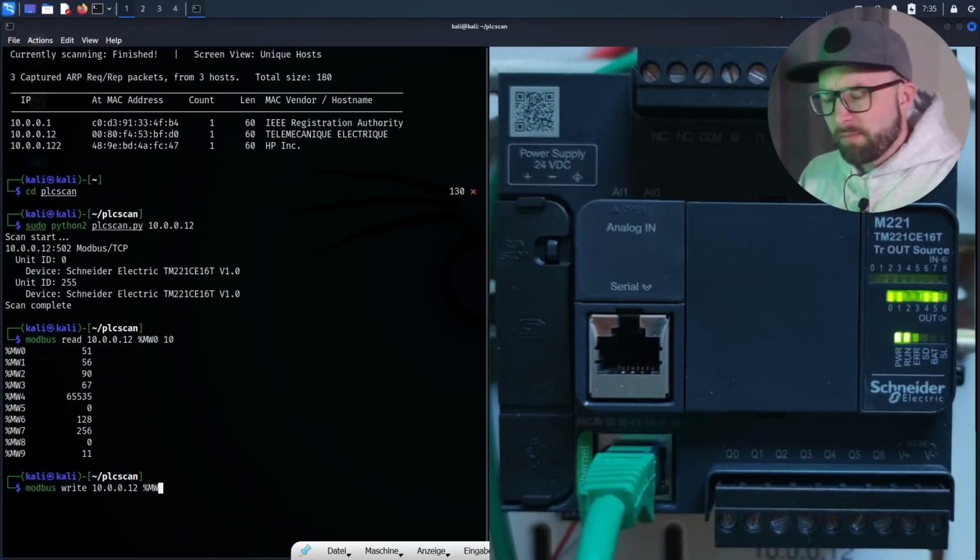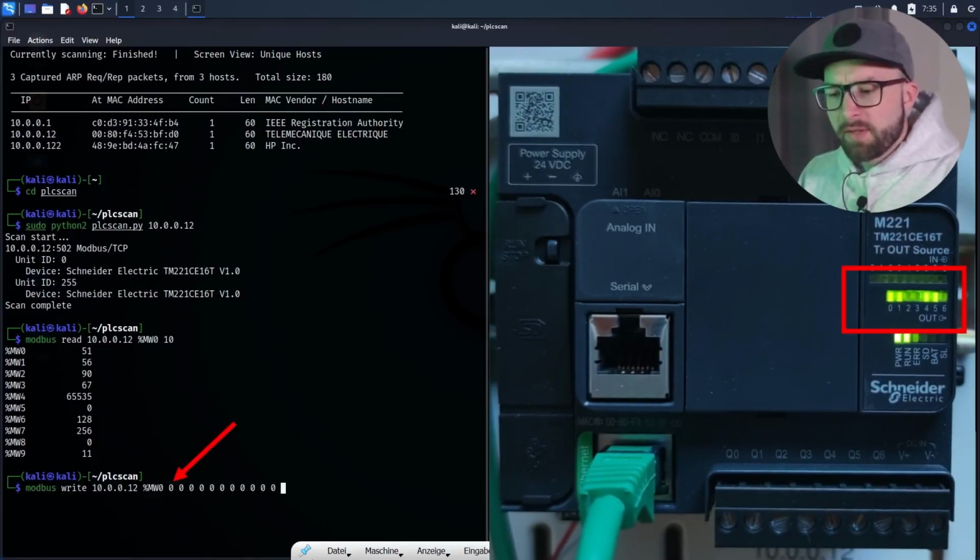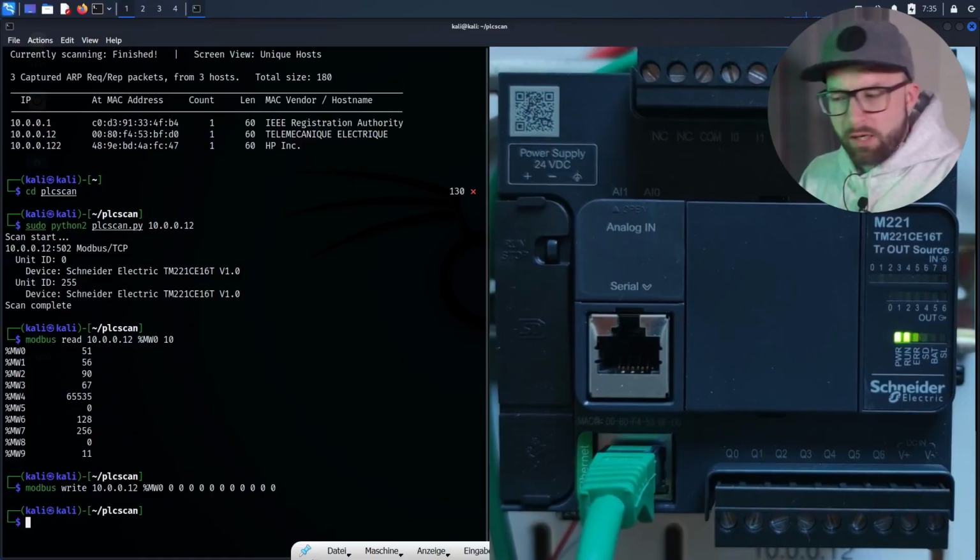In industrial control system programming, it is a common practice to buffer the output commands in the memory blocks. Thus, setting the memory blocks to 0 will result in switching off the outputs of the process control as well. The contents of the memory blocks are overwritten by zeros, resulting in switching off all outputs. All outputs are now switched off and the process control is in an undefined state and cannot react to critical conditions.